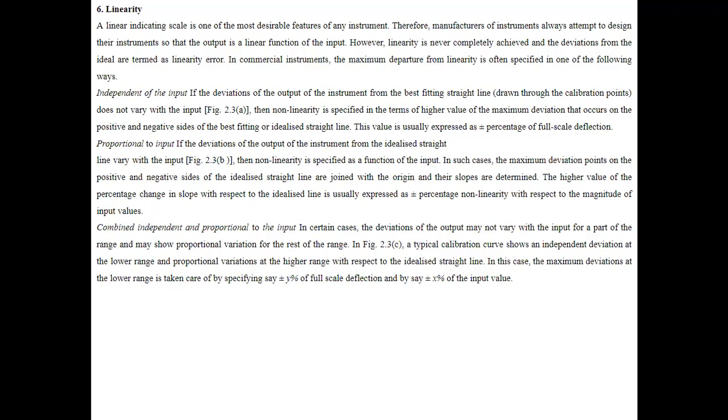In this case, the maximum deviation at the lower range is taken care of by specifying, say, plus minus y% of full scale deflection and by, say, plus minus x% of the input value. Therefore, these are the graphs for typical specifications of non-linearity.